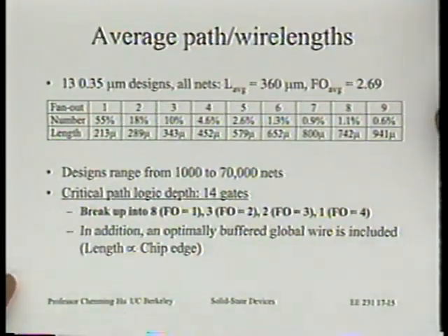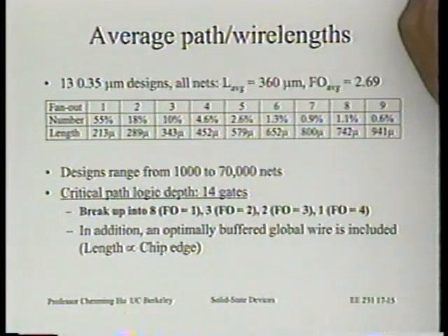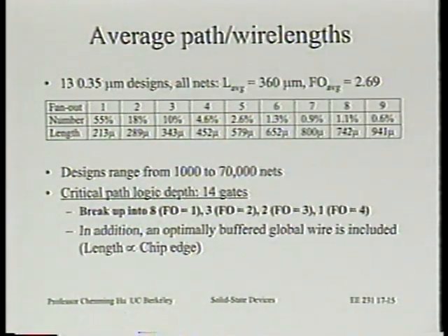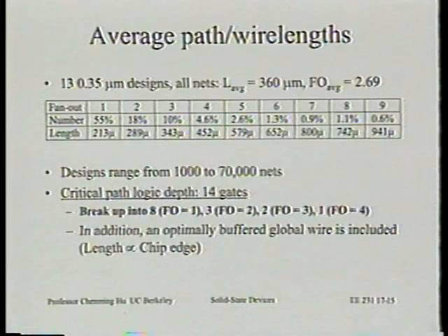Didn't you just show us a picture before where they threw it in acid and took out all the dielectric? Yeah, so that's the idea. Something similar might be done here. You may say, gee, why don't we just go ahead and do that? The problem is if you do that, do we really know that after some operation, these wires won't bend all out of shape and touch each other? Remember what I said about electromigration, how violent the force is? We're counting on this oxide to keep them in place, really. If you take it away, can you really trust them to be left alone? I don't think shaking vibration is going to be a problem, but internally it's a lot of force.